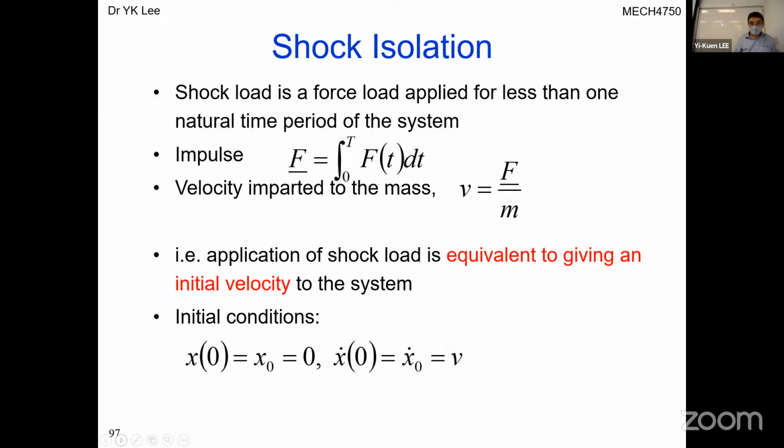Okay, here there's another quite important direction, which is shock isolation. As I mentioned, shock is very different compared with the vibration problem, right? Vibration has a harmonic force and causes a harmonic amplitude response. Shock happens in a very small period of time, and suddenly you have a large impulse force.